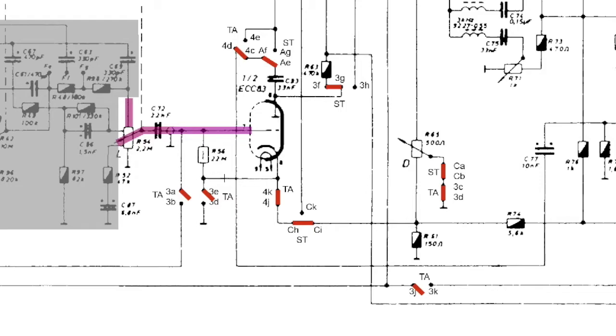There's that resistor over here, which is a 22 megohm resistor. It has to be connected to the cathode over there because that switch there is also open by the action of the pickup select switch, similar to that one. So this resistor here is effectively creating a negative voltage, a bias, at the grid of this triode. And the reason that works is because of the very, very high value here. The electrons that are basically leaked out of the cathode form a negative voltage over there, so it's a self-bias situation. It's one way of biasing a triode.